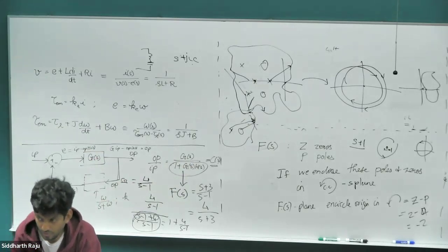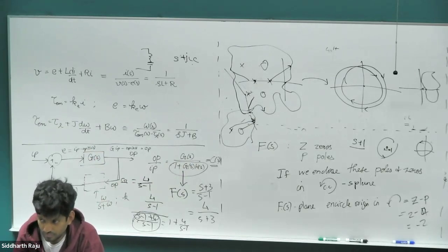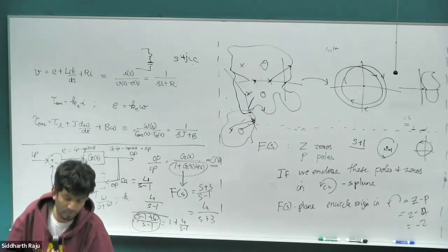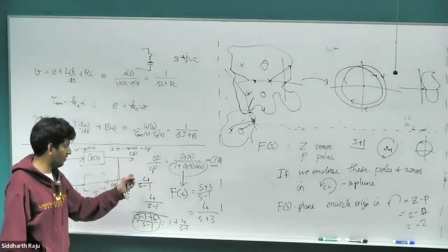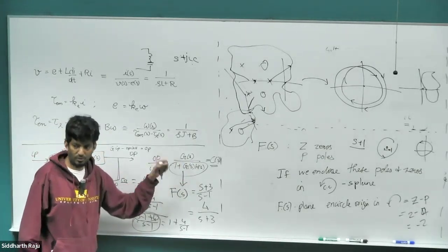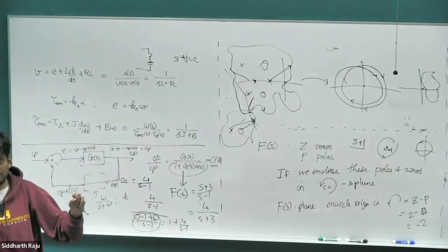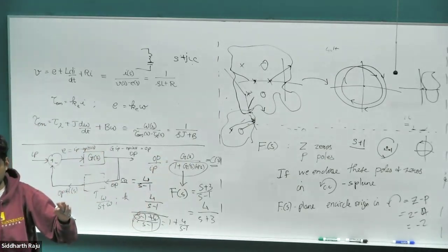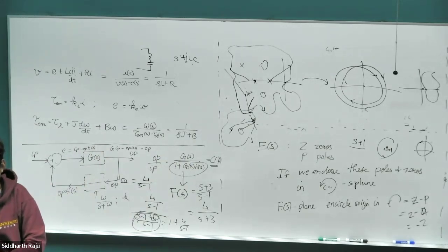You're saying that only the poles and zeros of the denominator of the closed loop system is what you're considering here. Is that correct? Yep. No, I'm not considering the poles and zeros of the closed loop system. I'm considering the zeros of the denominator of the closed loop transfer function. That's the only thing that would determine stability. Sorry if you already covered this, but do you have an intuitive explanation for why you don't have to consider the numerator in the closed loop transfer function?